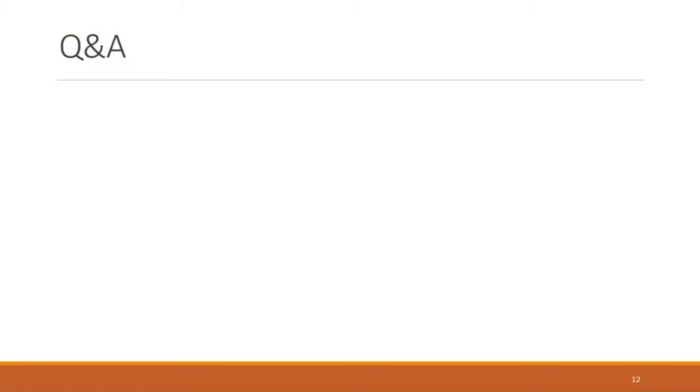Yeah, let me paraphrase your question, see if I'm understanding it correctly. So if you have an EPL file and you determine that the modeling capability is too limited and you need to export it to Energy Pro 5 full, and you export it to that full file, and you're seeing that it's populating with whatever you entered in Energy Pro Lite, and if you want to change that, sure. Like in the example of window geometry, that they're kind of all over the place, and you don't feel like you can average it within Energy Pro Lite. I guess I would preface this: if you can make it work in Energy Pro Lite, you can hammer it into some sort of average. Do it. It's going to save you a lot of time.